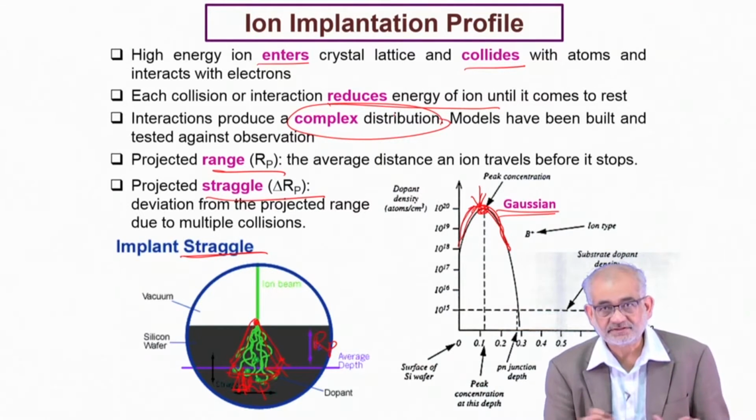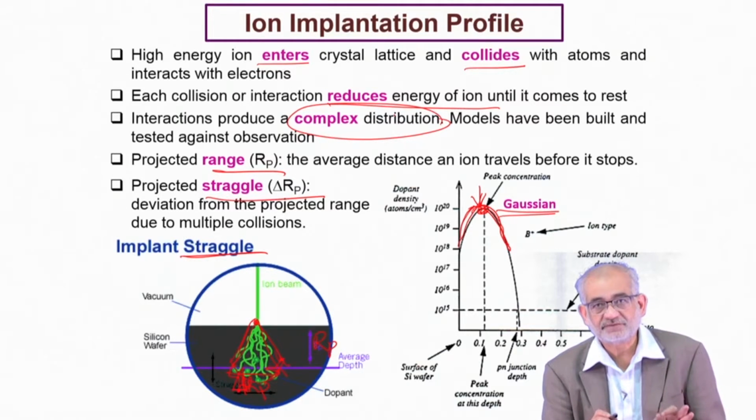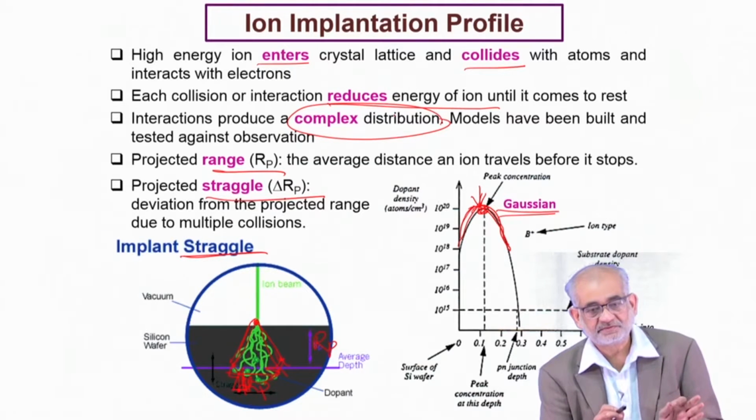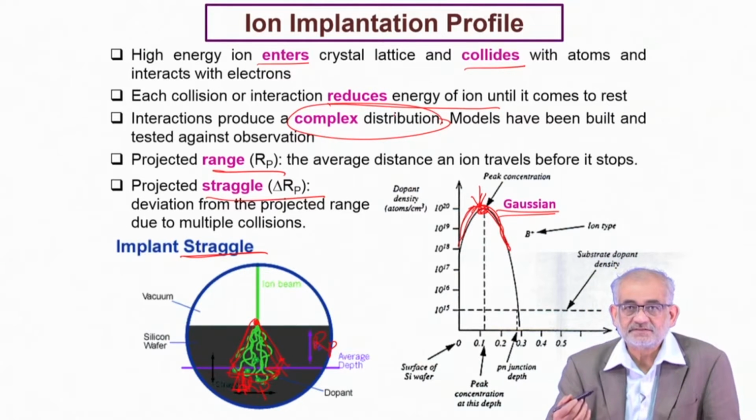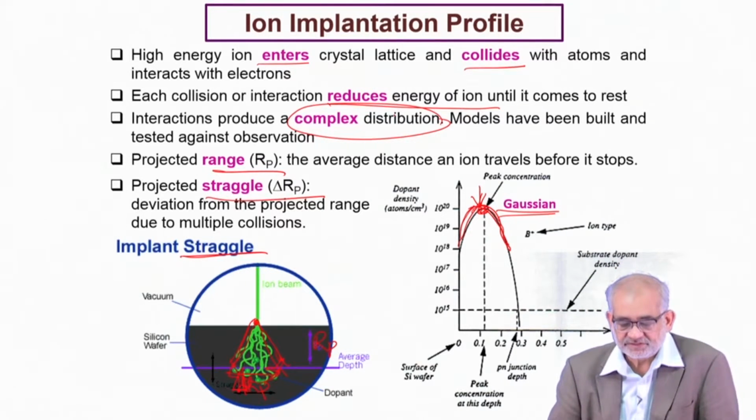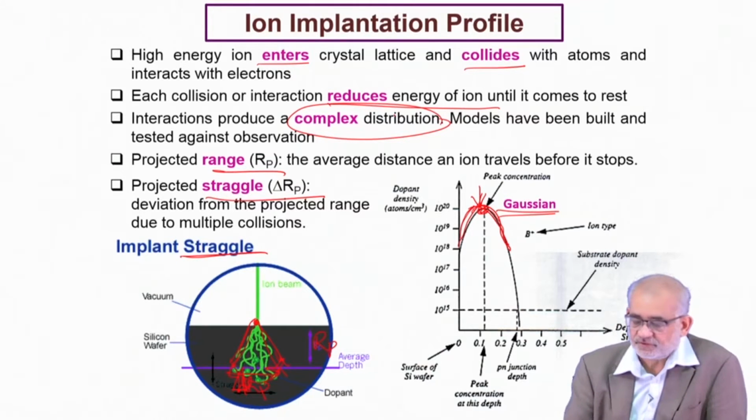What is the lateral diffusion or lateral spread of the ions? Say, for example, if you are trying to create a certain change in electrical properties of the semiconductor, you cannot afford to make it spread too thin along the lateral direction. Then there'll be leakage current and there'll be overall deterioration of the performance.